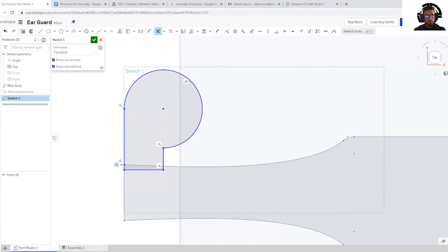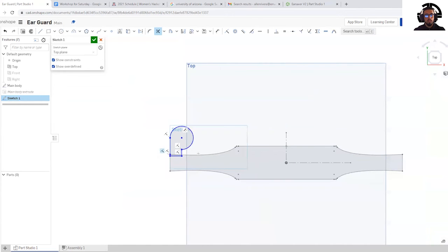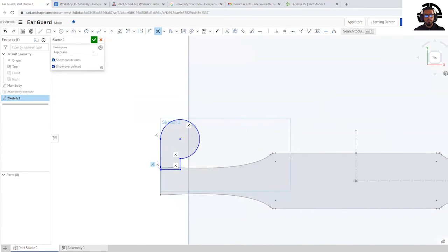Okay, so now I have a circle and I have this nice shape that really allows the mass to sit in here and also provide it to be under tension. But I would like to make, let's say, two of these, since this is a fairly thick option. So what I want to do is hit this button over here where the transform was, but I'm going to hit the drop down menu, and you're going to see an option called linear pattern.